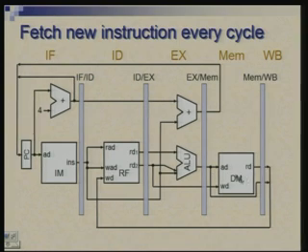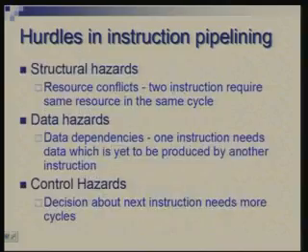Okay. For an add instruction, let us say there is an add instruction followed by store instruction. So it is this data which was the output of ALU, but it simply idled here and came here. This will be brought back to this through a multiplexer. So we will see those details a little more deeply later on, but the basic idea is that we incur this additional expenditure of more paths and more multiplexers, and as a result we can possibly reduce some delays and in some cases also eliminate them.